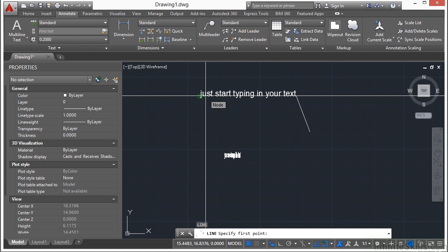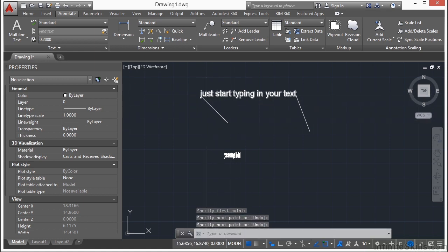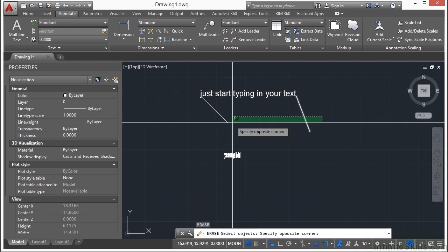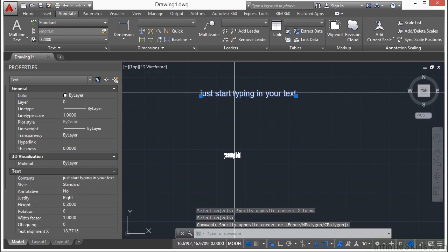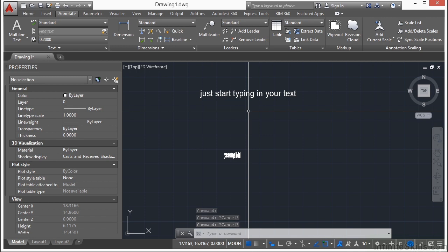Now over here on the left, I need to go to a node. All single text objects have a node, and that's always on the left bottom corner. Keep that in mind. And that's why you see 2 grips all the time. Now, text fonts are controlled by text styles. Text styles work just like dimension and multi-leader styles do. We're going to take a closer look at those because they're a little bit more in depth. But this is a quick overview of single line text.